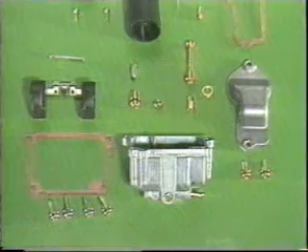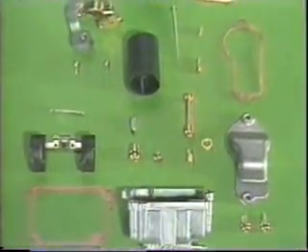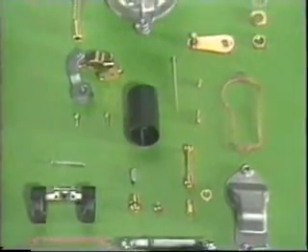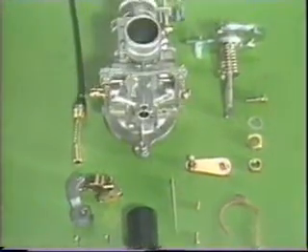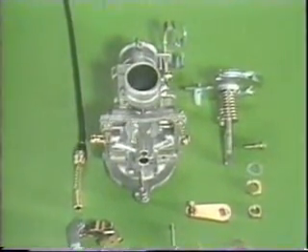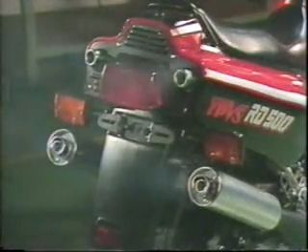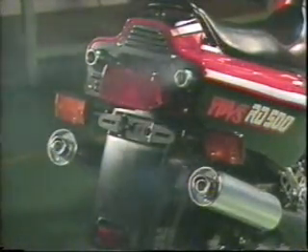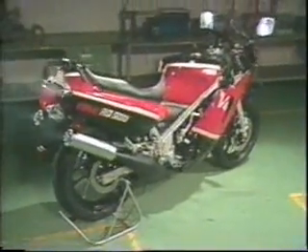Once you have identified the points, you can check these things. You must check if each part is adjusted to a standard setting, if the jet or air passage is clogged, or if it's loose. In this part of the service video, we are assuming a problem in the idle system at a low throttle opening range. Problems at the idle speed range may take a number of forms. For example, the engine may not start smoothly, or the engine may not idle smoothly. These problems can be caused by parts in the fuel system, YPVS, or the oil pump.